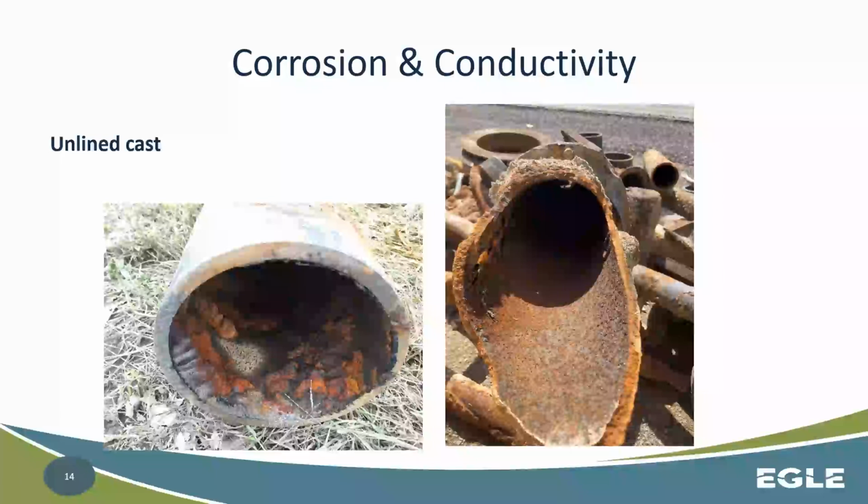You can have that rust factor leading to aesthetic water quality complaints, as well as a decrease in flow, especially if it's 4-inch cast iron or less. There's that likelihood that you're going to be losing that volume, and you're no longer delivering that amount of water or pressure to a given household, to the residents, right? Okay, so things to keep in mind, especially if your system has a history of not being maintained well.